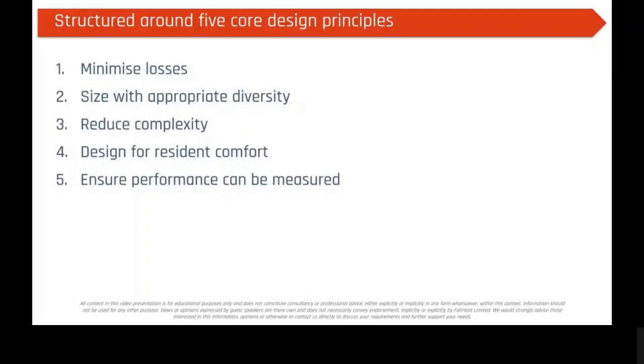They need strong justification, because every time we put in a hydraulic break, we have to have a temperature difference across that plate heat exchanger to transfer heat, and that raises my generation temperature. So that raises losses from a heat loss perspective, but from a heat pump perspective, it makes it even worse, because we want our heat pumps to be operating at as low a temperature as possible. So making decisions that reduce complexity and that are justified is also a key part of the document.